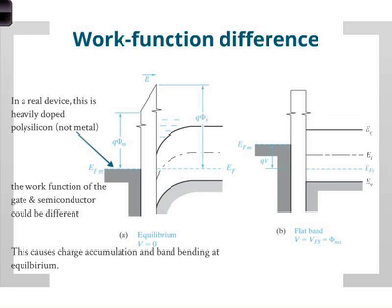Of course, what does that affect? The most important thing that it affects is the threshold voltage. So now you have shifted all the voltages up, which means the threshold voltage has to go more positive. You need to apply more voltage. You need to first get the flat band condition, then apply more voltage to get inversion. Okay, so it's an important parameter to keep in mind.